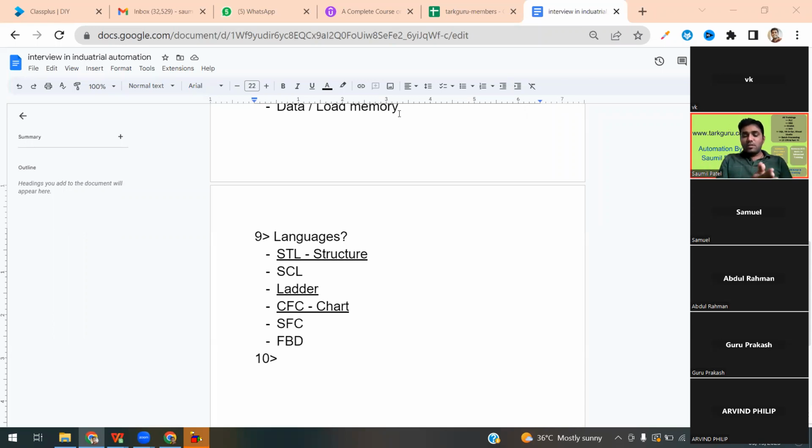Say you have set 10 milliseconds to execute OB35. Whenever the PLC scan cycle is running, every 10 milliseconds OB35 is called and run, then your cycle continues again, right? So this is the way you need to explain, but if you explain only 2 or 3 OBs, that is enough. I think Gulam Rasul, I have explained your question, right?